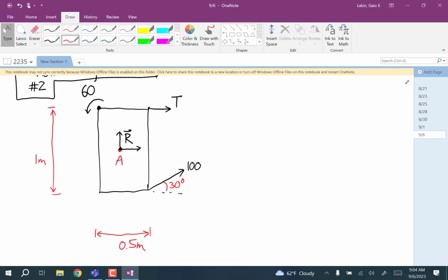The reason it simplifies it is then the row vector for those unknown forces is 0. And then when you take the cross product, it doesn't show up in the moment. But you can choose the about point anywhere, you'd get the exact same answer. In dynamics, that's not the case, remember, but in statics, that's true.